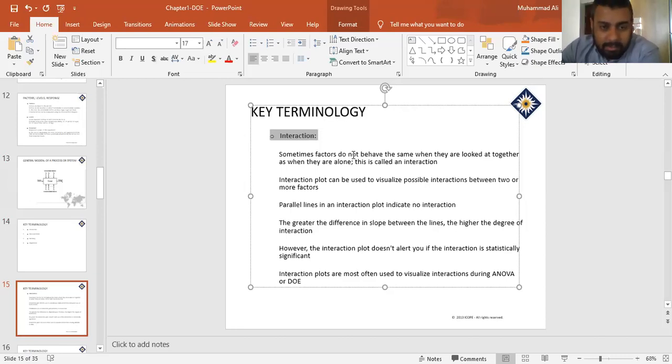Another thing I can tell you about interactions, for example, there are many chemicals that are not stable over 50 degrees centigrade. Okay, for example, you have a process where you have to go through 100 plus degrees centigrade, and then you are using some chemicals that are not even stable. So because of that high temperature, that chemical may not perform well, or will perform poorly, because at high temperature or high pressure, it will become destabilized.